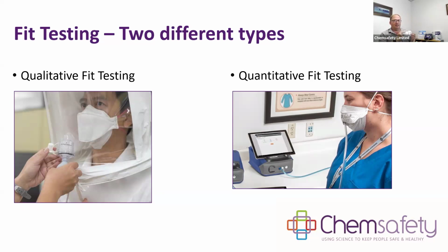It is more accurate. It does need adapters for your more permanent respirators, and disposable respirators can also be fit tested, but you need to put a little hole punchy type adapter in there, so they're not going to be suitable for use afterwards. And then you can just attach that probe onto your tubing and go from there.